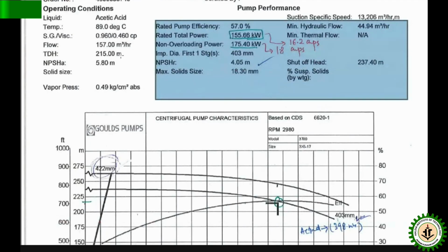Okay, if you give a specification of 157, they will not make a 157 pump design for you. They will give some available model that will satisfy the requirement. Maybe they have a model of 165, or maybe a model of 170, so that they will ensure that it falls within 80 to 100% of your requirement. So this way the selection is being done. It is not that you have 10,000 rupees, so you buy a 10,000 rupees mobile because it is available. It's not that. Same way it is applicable here also.